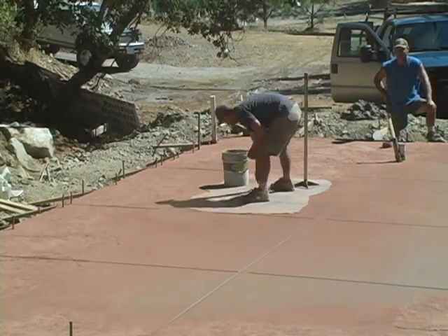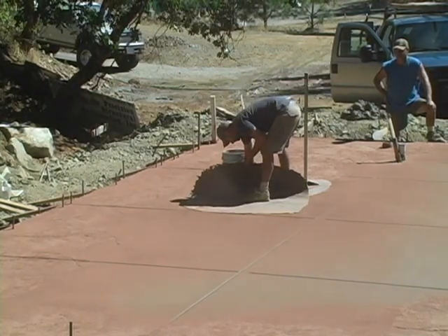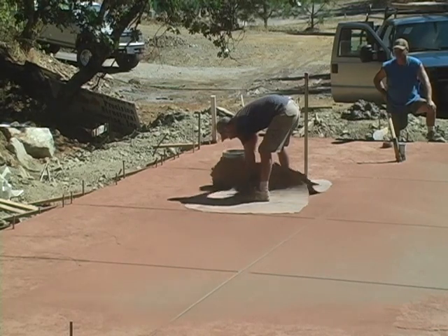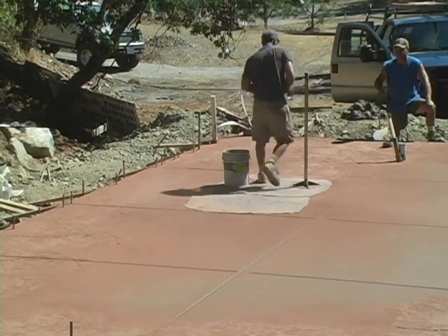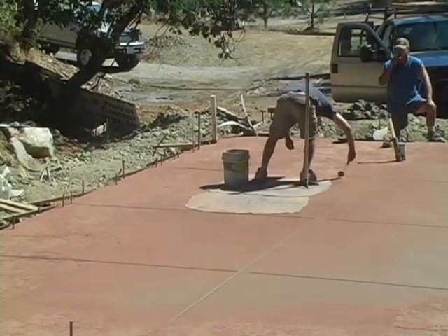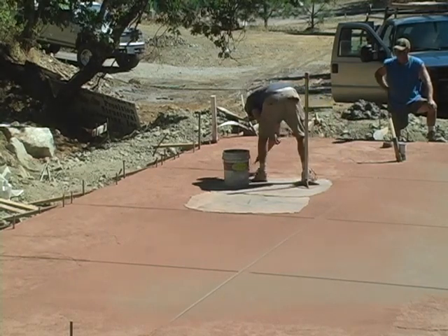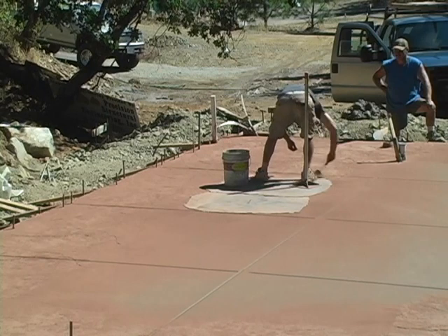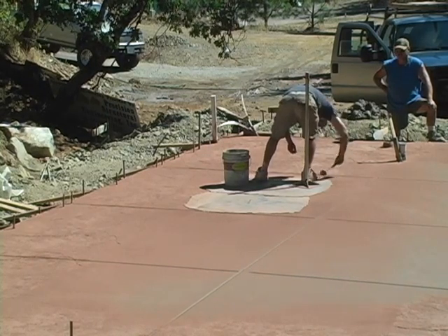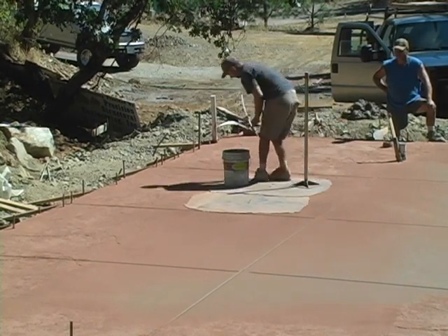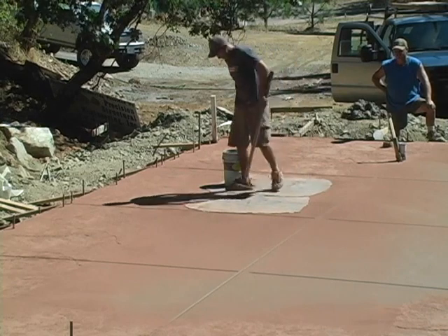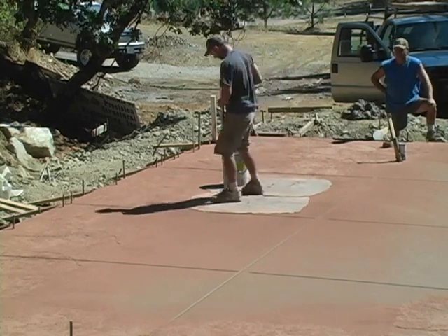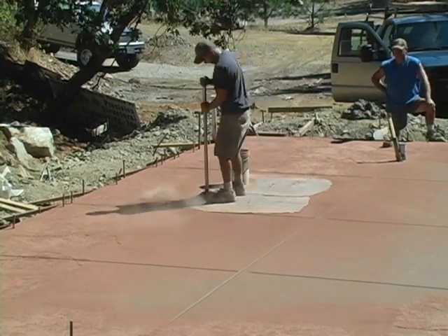And we're moving back down along that same line, going in the opposite direction now. So the idea is to keep moving and to keep shifting the way that you lay the stamps down. Like I say, turning it 90 degrees basically gives you a random pattern out in the field. If you use it the same way, it's going to be very obvious in the finished product. So that's really important to remember, to keep rotating the stamps 90 degrees as you shift them from one position to the next.